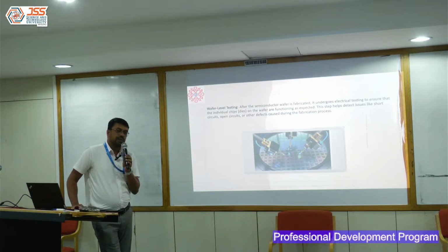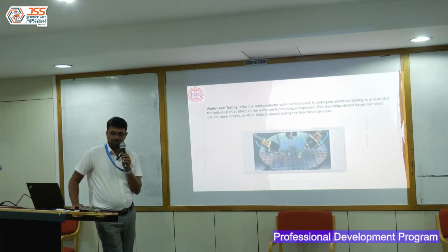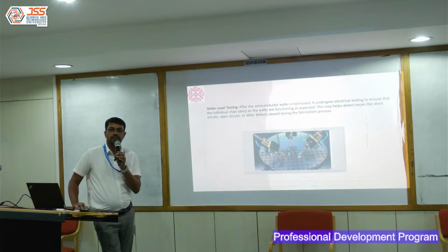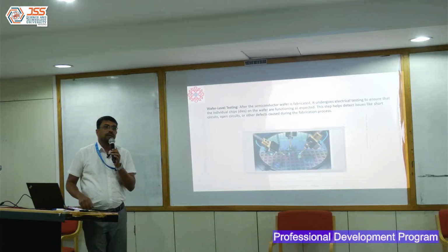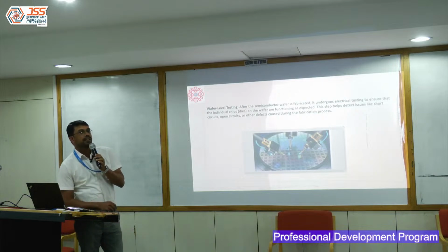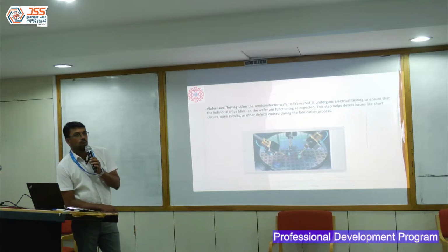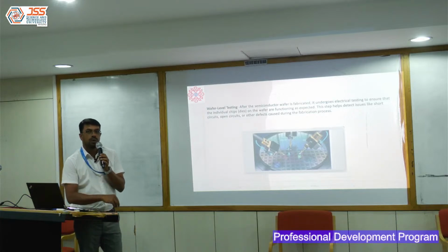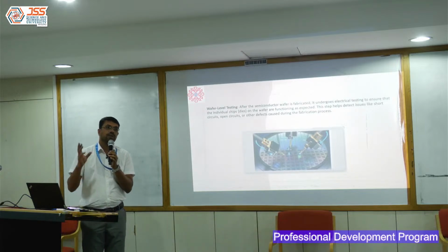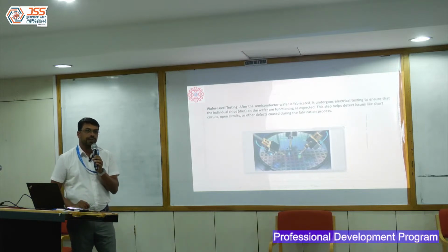Again, when it comes to testing, there are different types of testing. You might have heard about aging test. Typically, how do you simulate that aging? I want to understand how my components will behave, say 10 years from now. What they do is they put it in an oven and heat it up to a certain temperature for a few days.